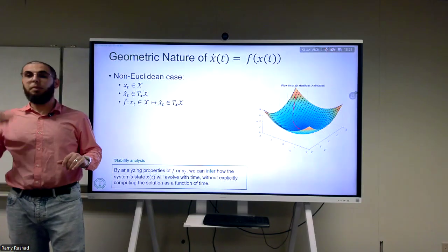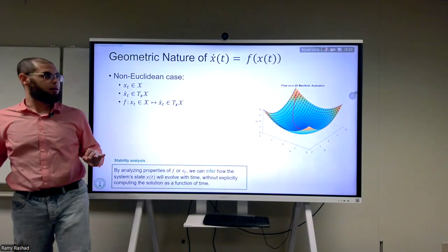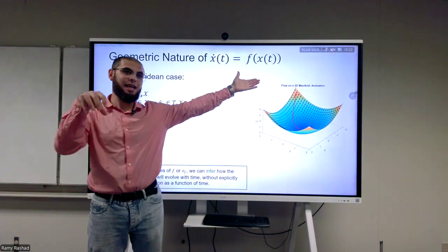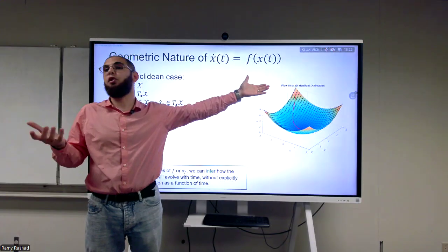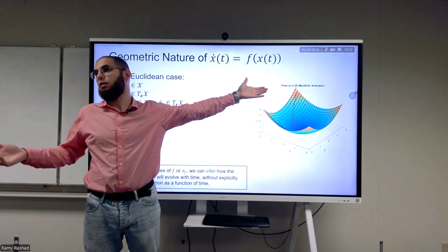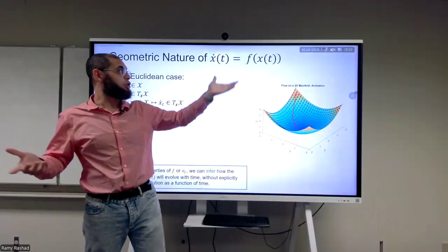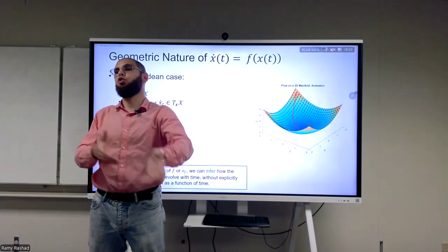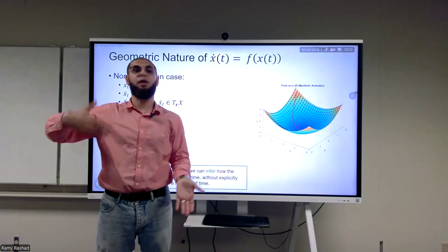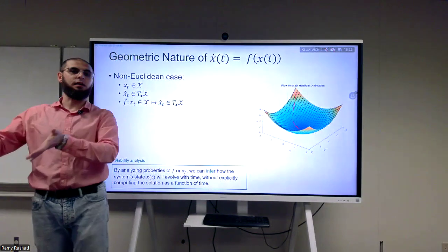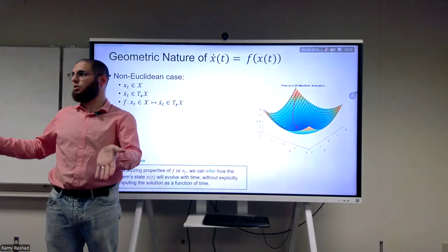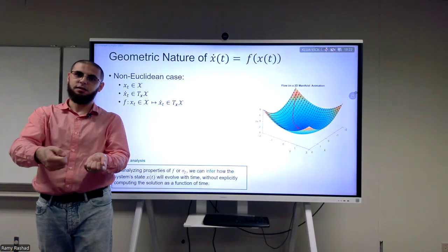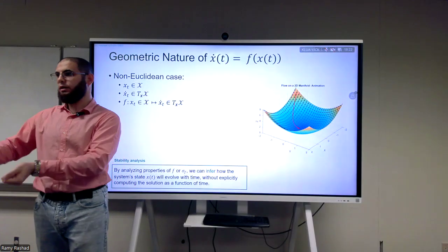By saying it like this, it means that if you give me this equation of motion, and let's say that you already have a controller inside and you want to test whether the controller is stable or not, I can just take the closed loop f and do stability analysis on it, and I can tell you whether the controller will be stable or not. This is actually a fundamental process when we do control designs in all systems and control. So whatever type of control you do, you should always provide the analysis that says that the controller is stable.